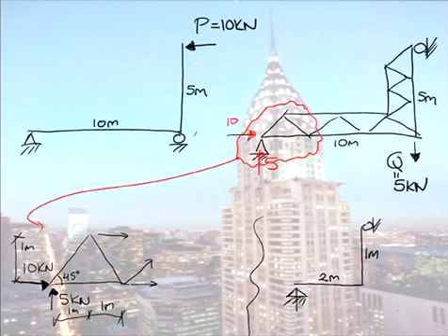If I work out these 3 member forces using the method of sections, I would get a negative value, so I'll draw it in its true direction, a 10 there. I would get a force in here of 5 root 2, and I would get a force to the right of 5. So the inwards facing arrows means effectively that's a compression force, and that's a tension force. Now, let's see if I can create that same system of 5 forces.